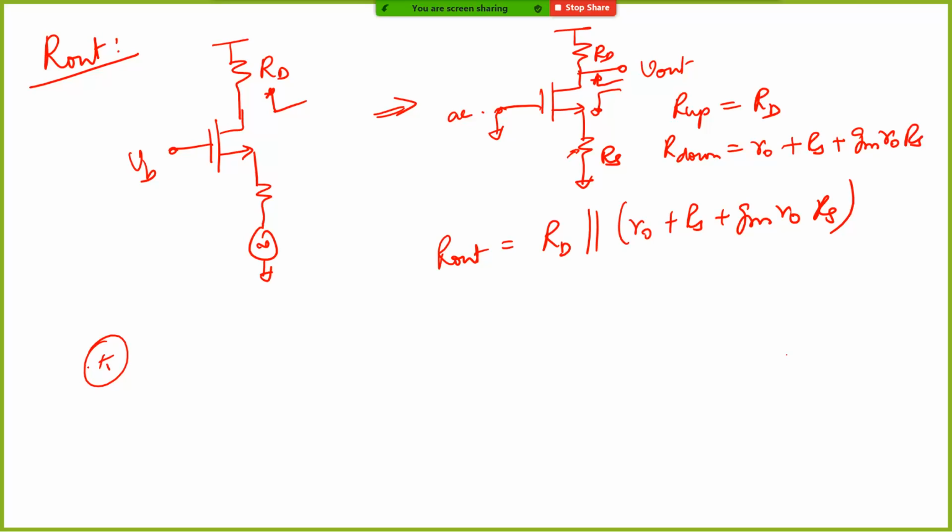I'm not sure, right? So this is the impedance of a cascode. All right, so the takeaway point is R out depends on RS, or in other words, the output impedance is also dependent on the source impedance, and the input impedance is dependent on the output impedance, or the RD or RL, whatever you have. This happens because the R naught is not very high, and there is this kind of a bidirectional thing that happens.